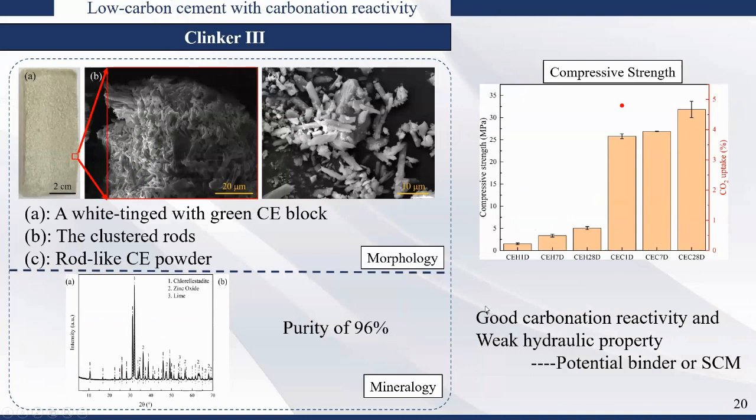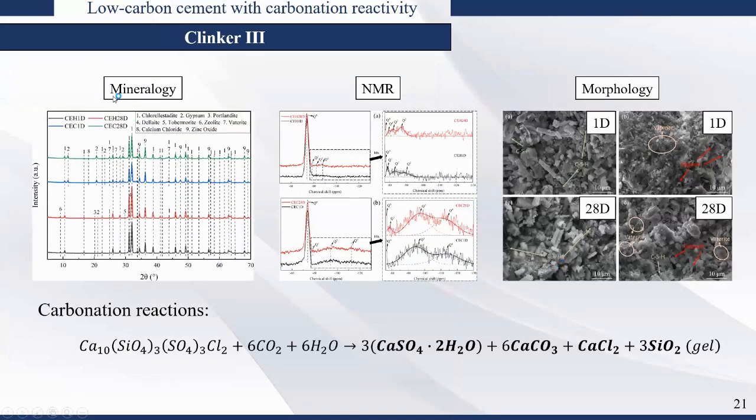We did carbonation and hydration tests on it, and we found it has only a very slight hydraulic behavior, around 5 MPa after 28 days. But if we let CE interact with CO2, the strength significantly increased to more than 30 MPa. So it shows that it has the potential to be used as an SCM or binder. We did mineralogical analysis using QXRD, quantitative X-ray diffraction, NMR, and morphology through ICCEPM.